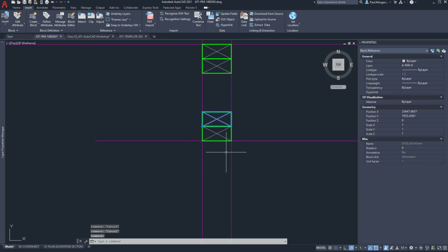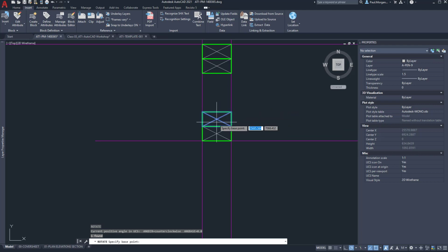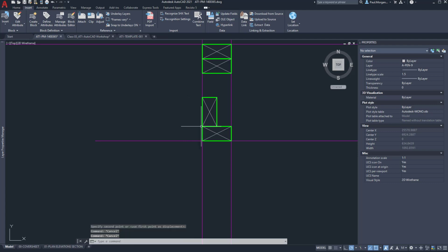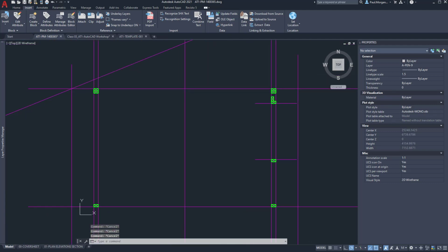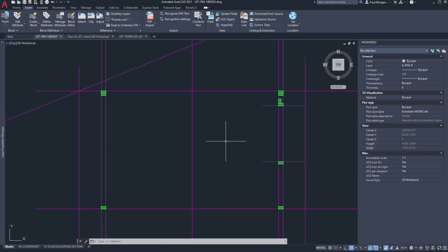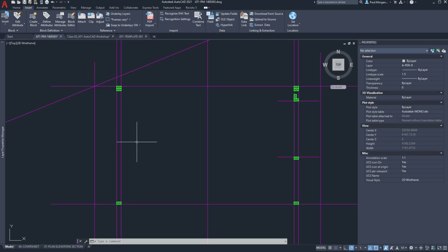Then what I'm going to do is click on this stud and go rotate. I'm going to click here and just move it up. And now I've rotated that stud, but now I do need to move it back to there. Starting to come together. Okay. Next up is a lot of reference plane offsetting to give us the truss that we want, and also give us our external walls. So let's start with just the external walls.